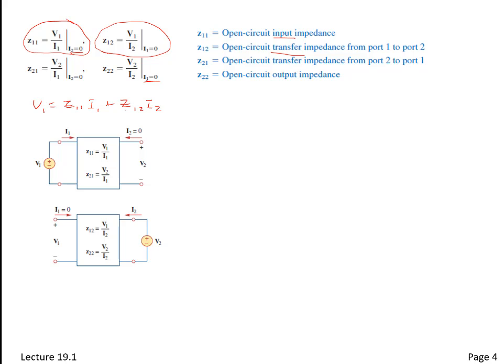If the driving point ones, V1 over I1 and V2 over I2, which are just a function of the values at that terminal, are the same, that gives you what we think of as a Thevenin impedance. If those are the same, we call the circuit symmetrical.